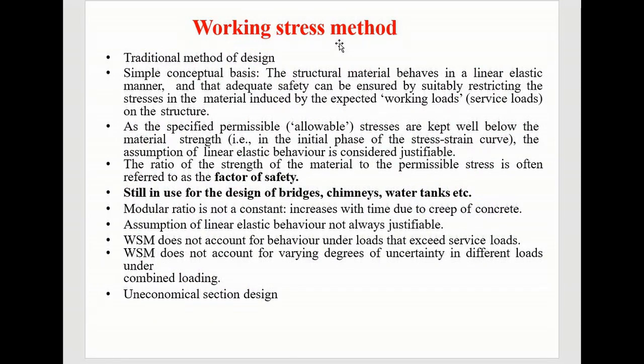This method is used for the design of reinforced concrete, steel and timber structures. In this method, the working load is considered for the design of structural elements with a larger factor of safety, and due to this larger factor of safety, the size of the elements will become oversized, and due to this it will be uneconomical.